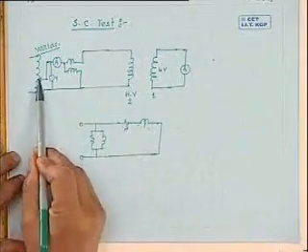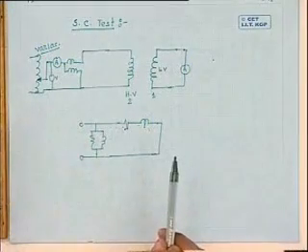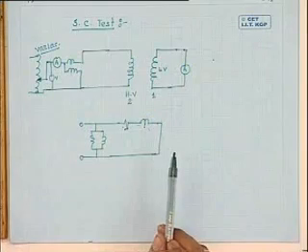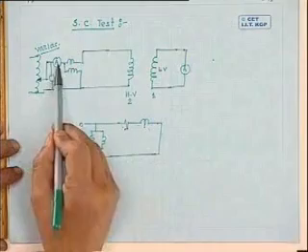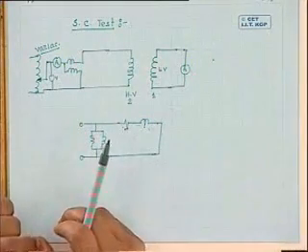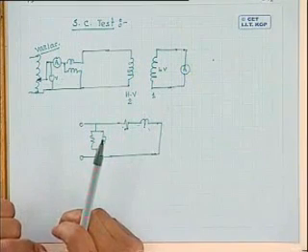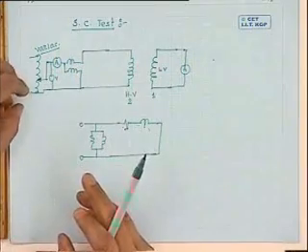So, what you should do during the course of the experiment, you set the variac setting at the 0 point so that you can increase the voltage from a very low value slowly. And keep an eye on your ammeter reading. You will find the rated current will start flowing at a much lower voltage because the secondary is shorted.